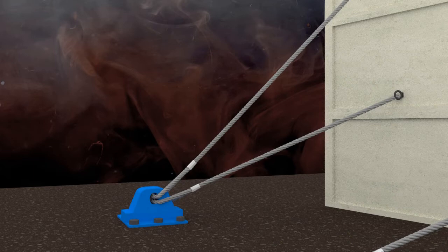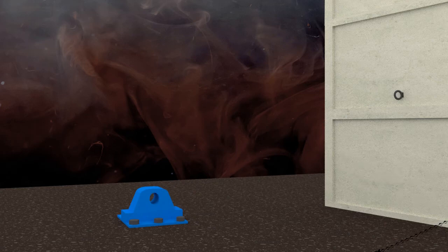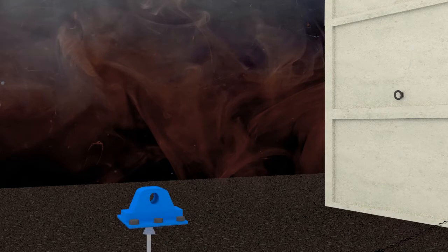There are two supports, one is the ground to which the bracket is bolted and another one is the rope. First of all, we will consider only the ground and ignore the rope. Ground restricts the movement of the bracket in the vertically downward direction, so a reaction will develop in the opposite direction and of equal amount as the weight of the bracket. But as the bracket is considered a weightless object, self-weight is negligible and so the reaction from the ground is also equal to 0.